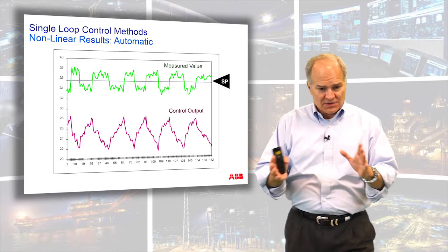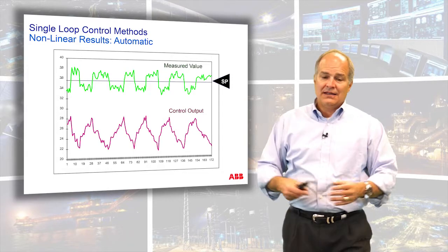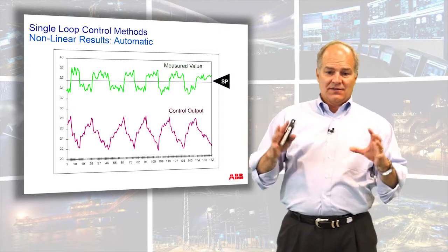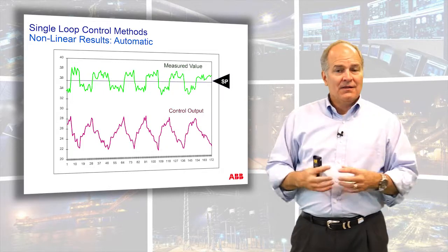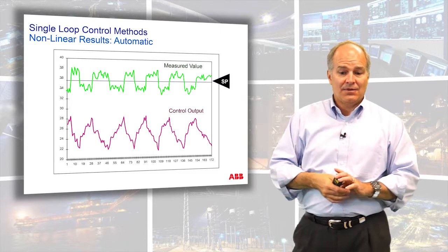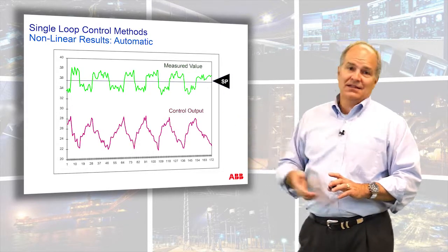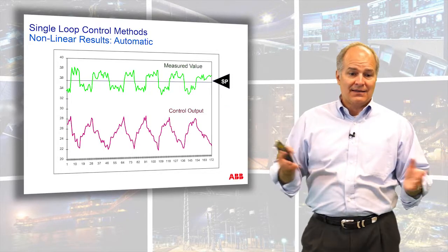I'll go and look at the actuator, and if it has a valve positioner, you'll see it kind of jump back and forth. A lot of times that's just a sign that the valve positioner is worn out. They usually have a cam on them, and maybe they're stuck. Or maybe it's got fingers or gears that get stuck, and they break. Those are things that need to be fixed mechanically. You can't fix that with process control or by adding a deadband.